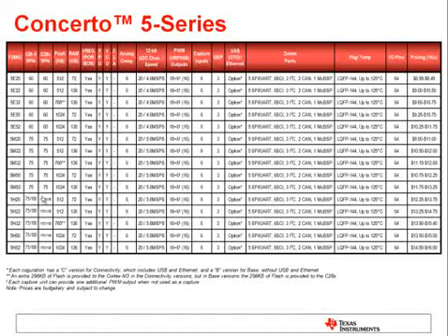Another variant to point out is the 768K of flash. In all the other configurations, flash is divided 50-50 between the 2 cores. So 256K per core in these devices and 512 KB per core in these devices. In the 768 KB configurations, it's still the base 256 KB per core.